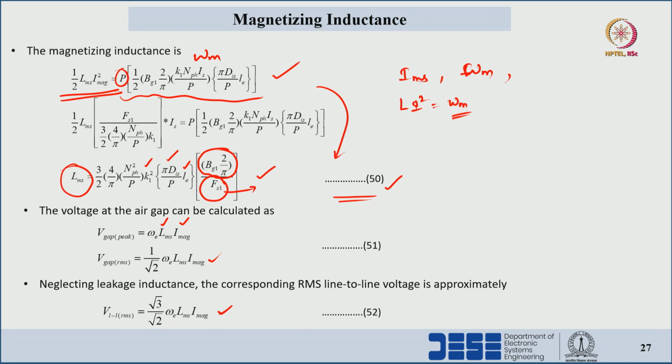So, by calculating these voltages at the air gap, we can modify the required supply voltage. With respect to the required supply voltage, we can find how much maximum value of Bg is possible and how much MMF is possible at the air gap. The MMF required to establish the actual flux density at the air gap, we can recalculate by knowing the voltage at the air gap.